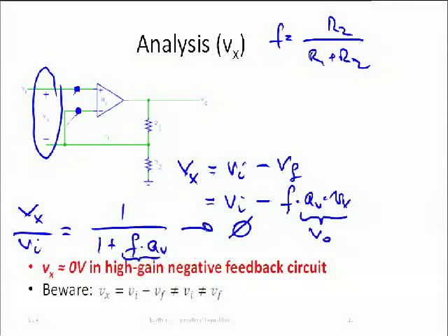Well, it would be infinite, right? Because that's not the case, V out is not infinite, that would be useless. So the only way we can get, with an ideal operational amplifier, a finite voltage at the output, is that this voltage Vx at the input has to be 0.